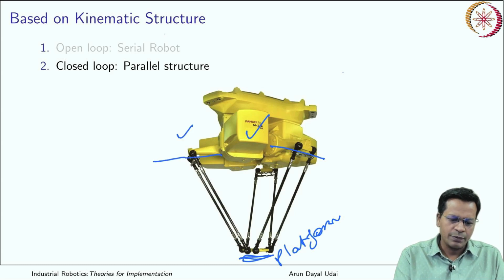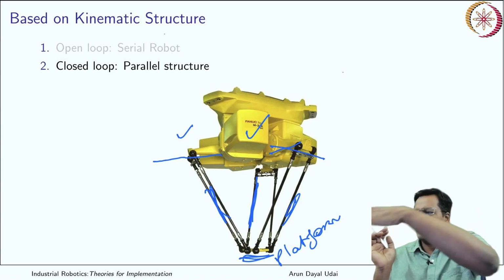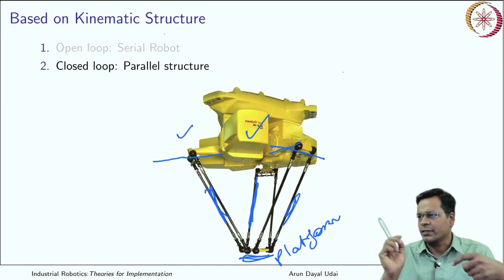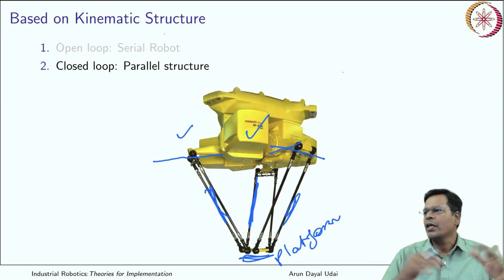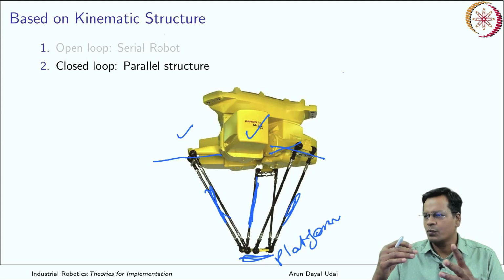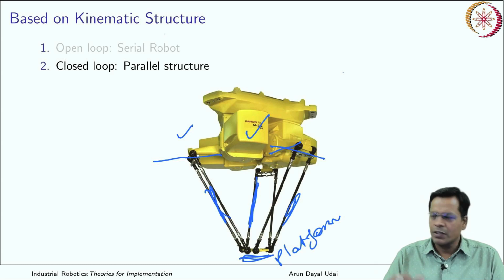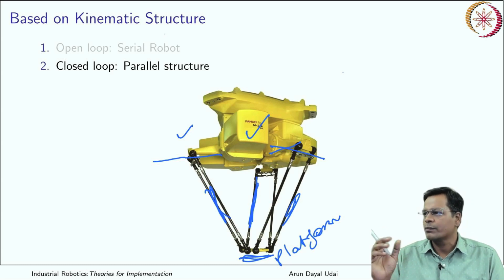So all the levers you can move, and finally this can go up and down, this can move, and that makes this platform go anywhere along X, Y or Z directions. Okay, so this is a parallel robot when all the 3 are moving simultaneously. I'll show this in operation while discussing serial and parallel robots in one of the lectures in this module.